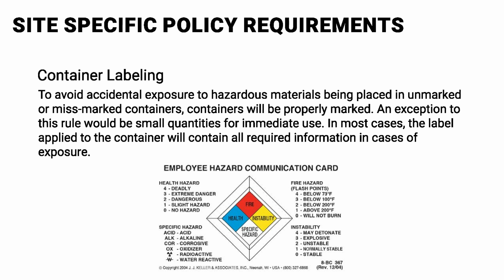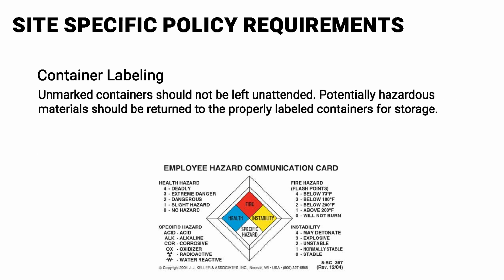Container labeling. To avoid accidental exposure to hazardous materials being placed in unmarked or mismarked containers, containers will be properly marked. An exception to this rule would be small quantities for immediate use. In most cases, the label applied to the container will contain all required information in cases of exposure. Unmarked containers should not be left unattended. Potentially hazardous materials should be returned to the properly labeled containers for storage.